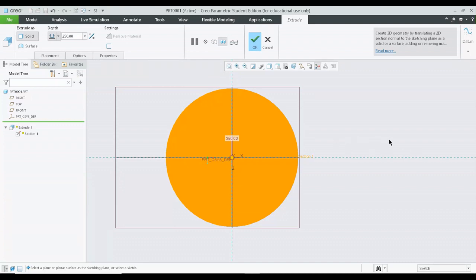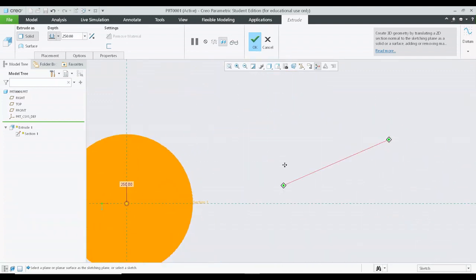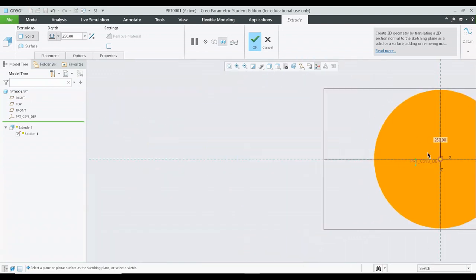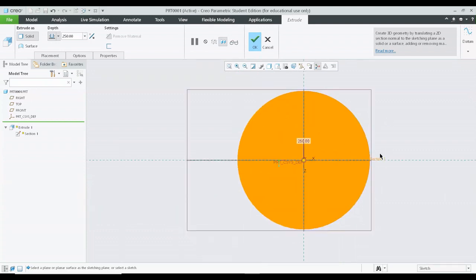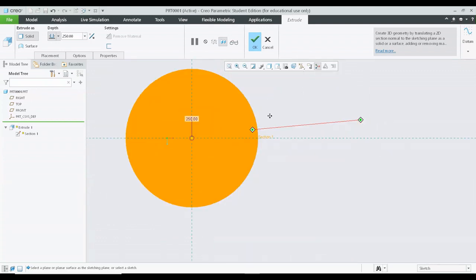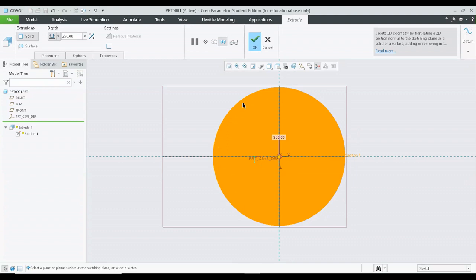In order to pan the geometry, we can press shift command on the keyboard, and we can press the middle click, and we can move the mouse in any direction. So this will basically pan the object or pan the model. So this is another option that we are learning while creating a solid model.